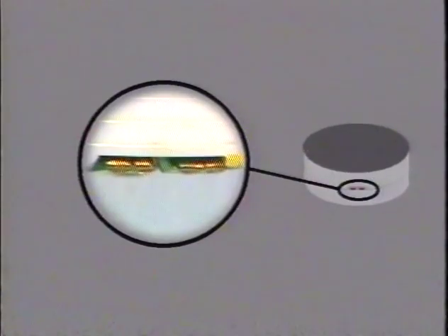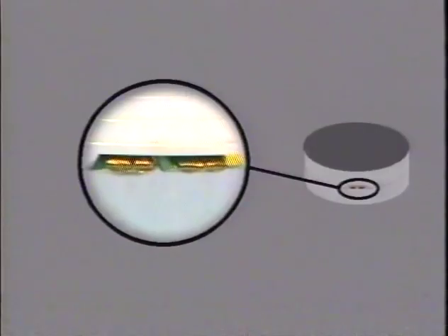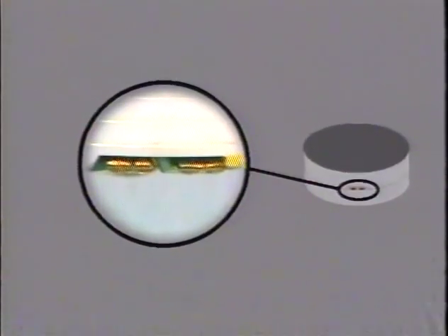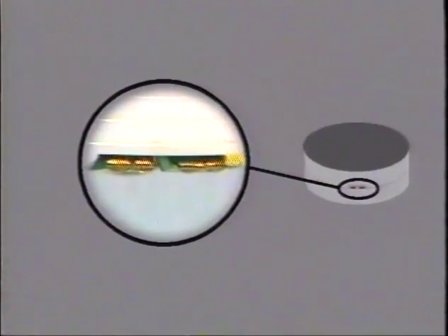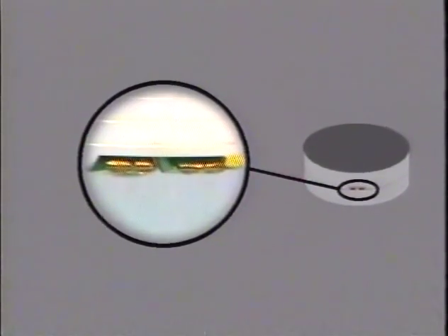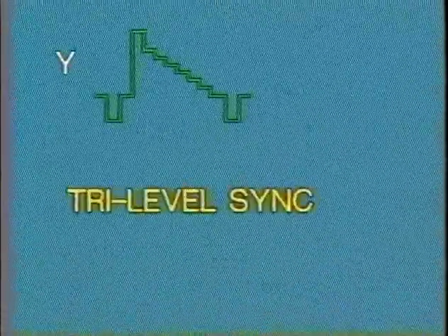It is interesting that although the heads are part of the same block, they will have different time base errors. Therefore it is necessary to have separate sync references on the tape for Y and C, so that they may be correctly timed relative to one another to give a coherent playback image. In the Y channel, the conventional sync pulse is replaced by a tri-level sync.